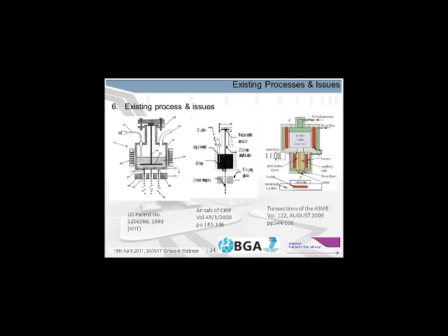The next was an innovative system. This is again from 2000, and an innovative system where you can see a piezoelectric sleeve. So instead of an actuator which mechanically pushed out the solder balls, this one here squeezed them out one by one. The advantage of this is that you can place them almost in an inkjet type technique.